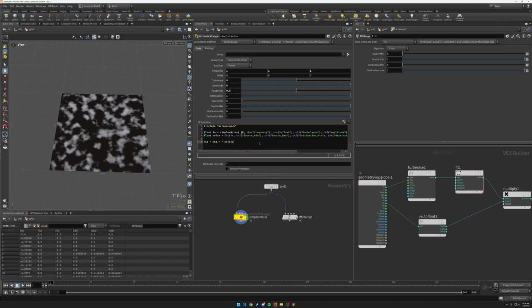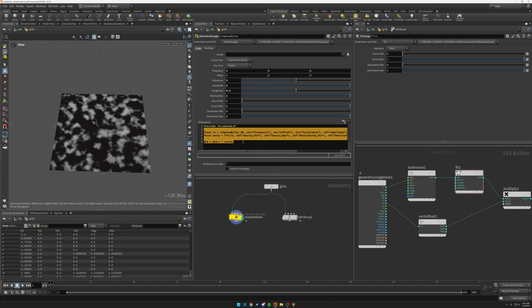And for simplexNoise, I'm using this all the time now. And I'll probably build a couple others as I continue to use a couple other noises. Like I've been using curl noise quite a bit lately, and I'll probably do something similar. But I haven't seen anybody really pointing out how easy it is to get this going in VEX, such that I can then go change and use VEX to do everything I need to do. And at this point, I don't have any reason to jump into the attribute VOP land.